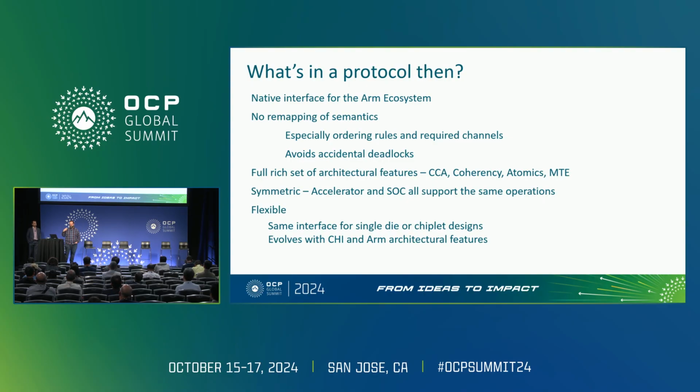And it also lets you potentially think of other designs where maybe you put some SoC functionality into your accelerator chiplet. I think somebody was talking about beachfronts in an earlier discussion. You may need to put some of your memory interfaces in your accelerator, and you want to treat that like host design. You really have an option to do that because you can put some of that functionality across the two different dies. So what's really the advantage of this protocol is that it is a native protocol for how you're doing system and SoC integration, and that lets you pick where you want to put something within the system.